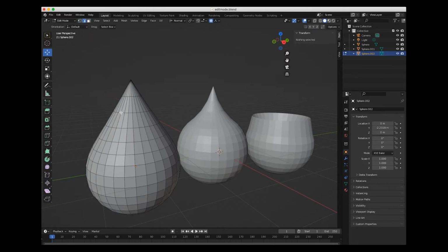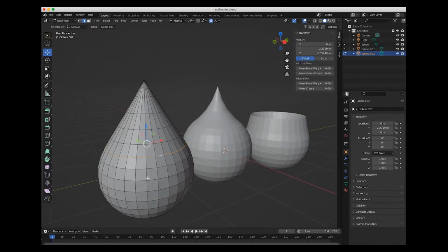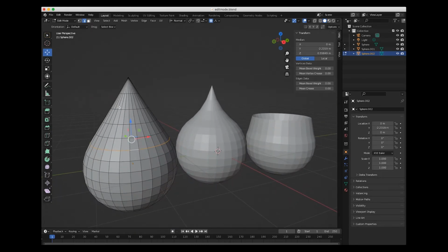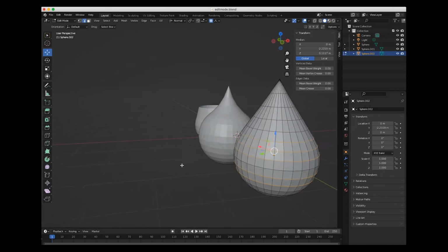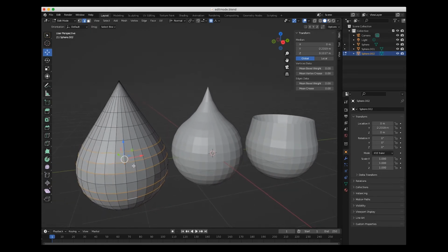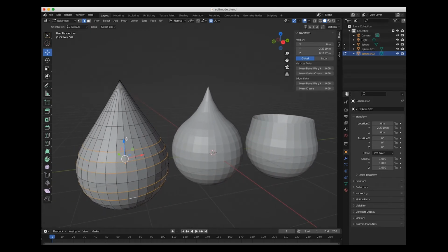So I'm going to edges and I go on top of an edge and press the Alt key and select. So I selected the entire loop. If I want to select another loop, I just press Shift key and then Alt key and I keep going, right? And I can select the loops. So you're always going to select the loop that's continuous, until you find a quad face.